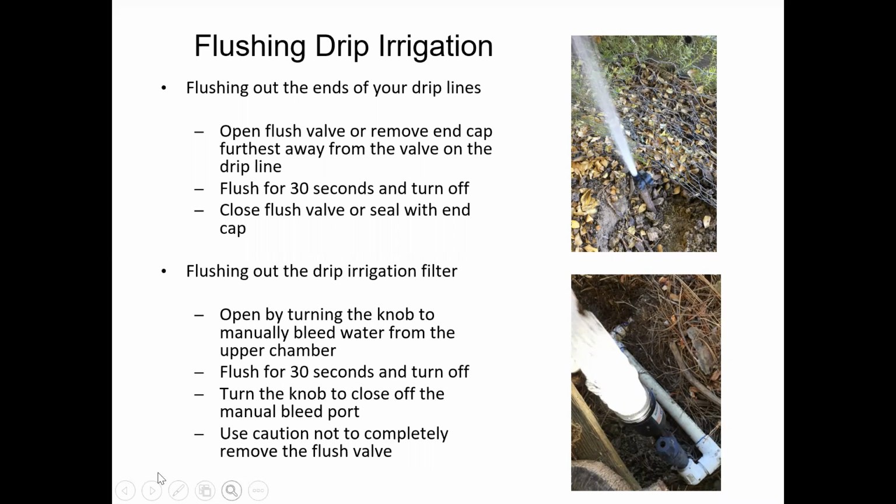One thing to keep in mind, be careful as you're flushing that, moving the flush valve, that gray piece at the bottom of the picture, make sure that you don't fully remove it. Otherwise, you're not going to be able to control the flow of the water as you're flushing things.